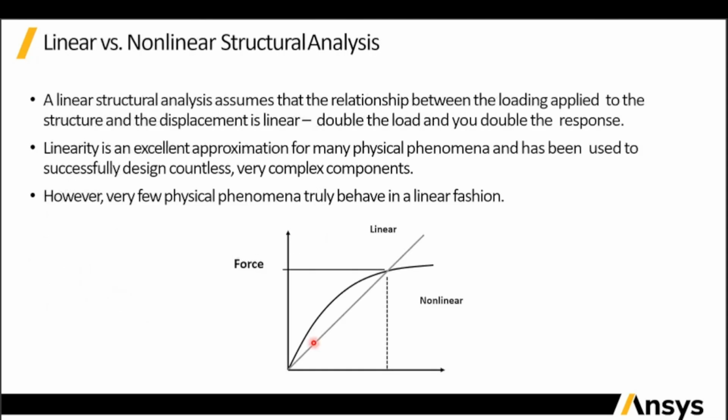So what is linear and what is nonlinear analysis? A linear structural analysis assumes that the relationship between the load applied to a structure and the displacement is linear. It means that if you double the load, the response or displacement would also double.